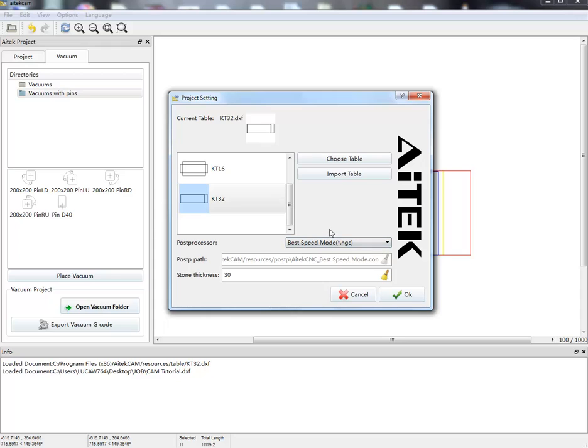best speed mode. Best speed mode is good for sync cutout, because the machine needs to keep a constant speed to achieve good finishing on the corners. The exact path mode is used when the machine needs to work sharp corners. For example, an island, or a kitchen top with two polished sides. This mode will respect the G-code positions even if it has to come to a complete stop. This will allow the machining of sharp corners.